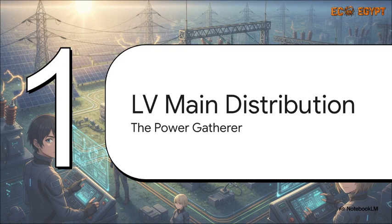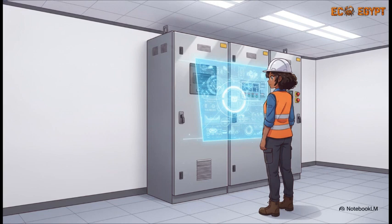Moving right along to Section 2, the LV main distribution board. Let's look at the low voltage side first. Think of the LVMDB as the primary gatherer of energy from your solar inverters. When you're pulling power from a whole block of PV inverters at 0.8 kilovolts AC, you need some serious muscle. So it uses two massive 4,000 amp air circuit breaker main incomers to handle that load. Plus, it can take a 50 kiloamp short circuit hit for a full second. It's housed in an IP54 indoor enclosure to keep out dust and moisture and uses a TNS solidly earthed system.